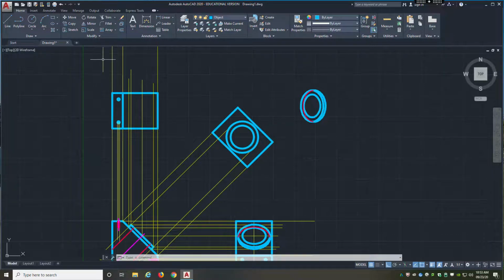And the best way to do that is to offset. And 2.125 is the correct number. So let's offset this bottom up like so. Change that line to a construction line, hitting escape, and then I'm going to move, right?